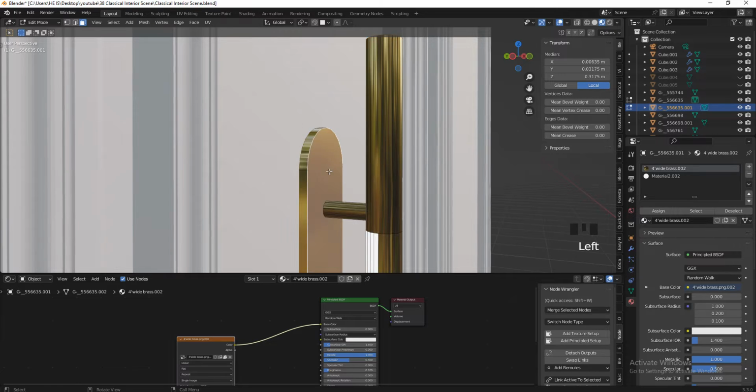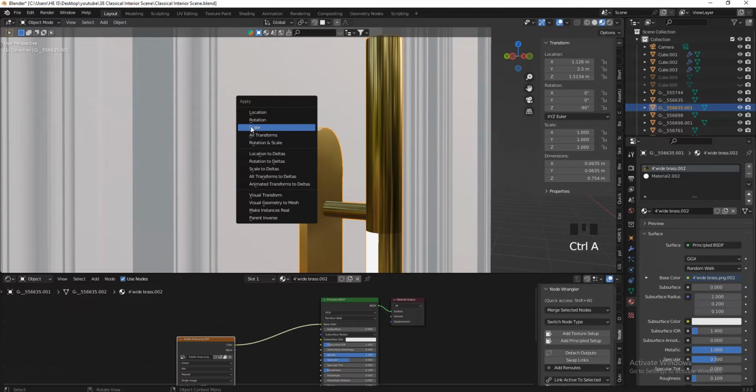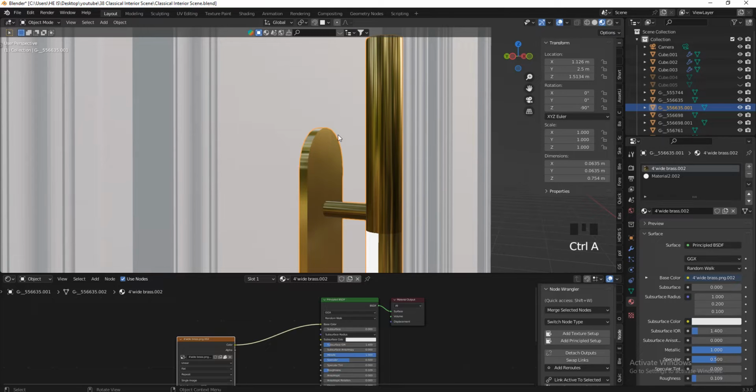So after that, I'm going to select this face, and let me get outside of the edit mode first. Make sure that the scale is applied. If the scale is not applied, if we try to bevel it, the bevel may not be applied correctly. So apply the scale. So in this case, it's already applied, so we don't have to worry about that. But to apply it, press Ctrl A and choose scale, in case you don't know it. As you can see, if I press Ctrl A and scale, we have this option: create new object data, users, and apply transformation.